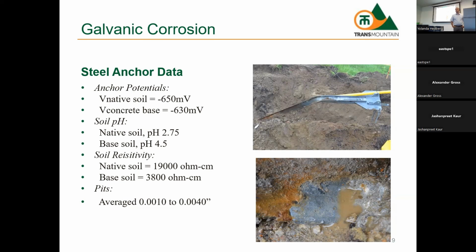A lot of designs that we're running into right now deal with what we call AC mitigation systems. Where we have pipelines that share the same right-of-way with overhead power lines, you're inducing an AC voltage onto the pipeline. So we intentionally ground our pipeline using copper, either a copper cable in the ditch or a copper rod.